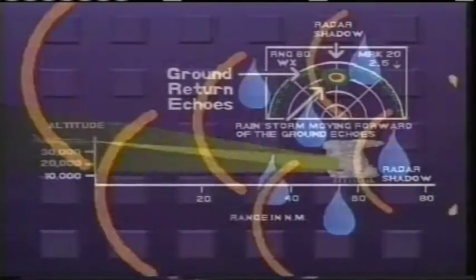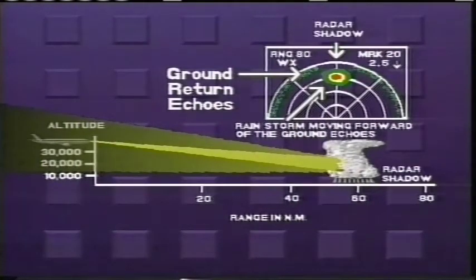As a pulse of radar energy travels through a rainstorm, each raindrop scatters a small fraction of the pulse's energy. The more raindrops within the rainstorm, the more of the pulse's energy is lost to this phenomenon. An intense rainstorm will disperse all the available pulse energy within a very short distance, as little as a couple of miles. Once this occurs, the radar's ability to detect targets beyond that range is completely exhausted. This energy loss phenomenon is referred to as radar attenuation.